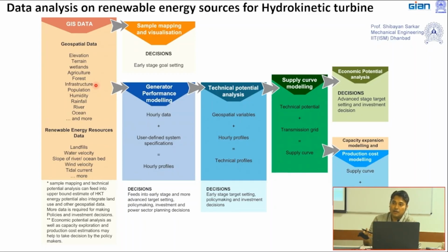How is the terrain, whether you need to excavate this area or site, or need not excavate, where you will be putting your plant, where you will be putting the civil structure, and how you will be distributing the electricity which will be generated, and if required, where you will be storing the energy in a battery. All these things you have to do through the field survey. So this type of data is required, and this type of analysis will be done.